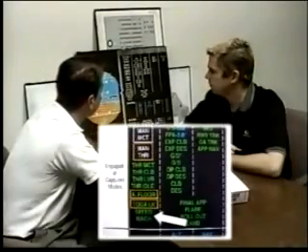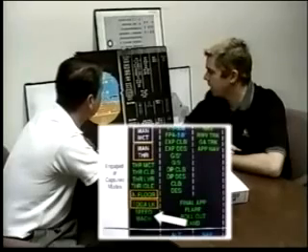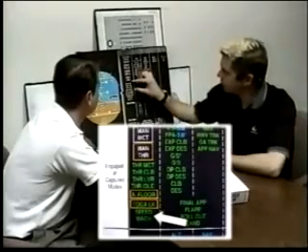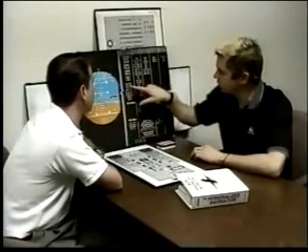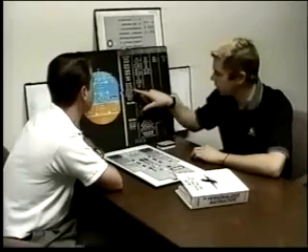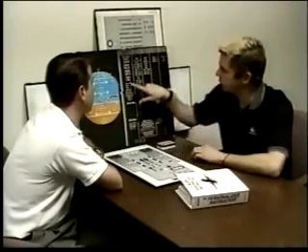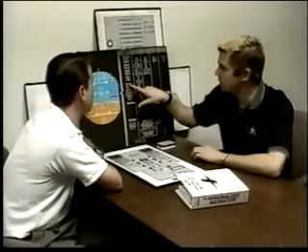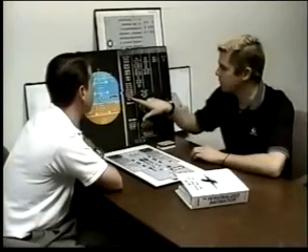Speed Mach. Explain those FMAs to me. Speed Mach is completely different from these other engaged modes. Speed is the only mode where you have a range of thrust available. In all these other cases where it says thrust MCT, or thrust climb, or thrust idle, or even thrust lever, you are only getting the thrust that's named there. I have MCT thrust only. Down in speed, I get a wide range of thrust.